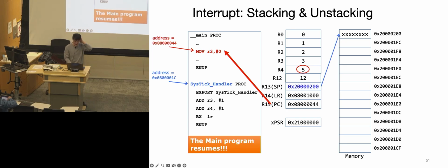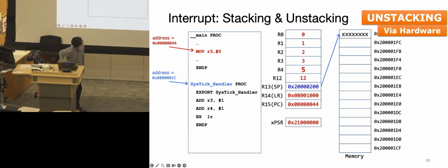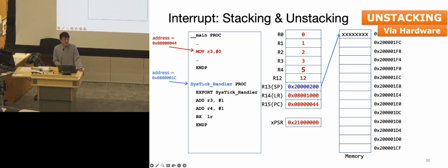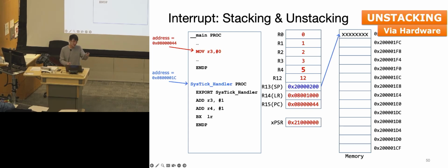Yes. When the system interrupt handler is storing the special registers, if it causes a stack overflow exception, does it just terminate the interrupt and go back to the program, or does it just crash? That's a very good question. Usually it crashes. Any other questions? Unless you wrote a function to specifically handle that, so when that exception happens, it does something. Usually it prints out an error message. Any other questions?